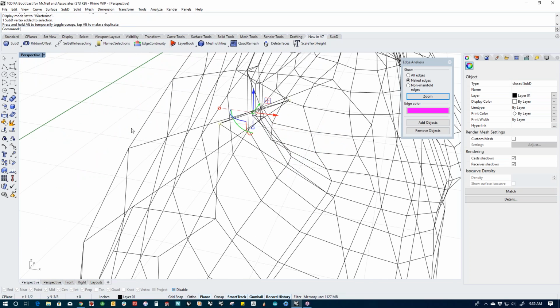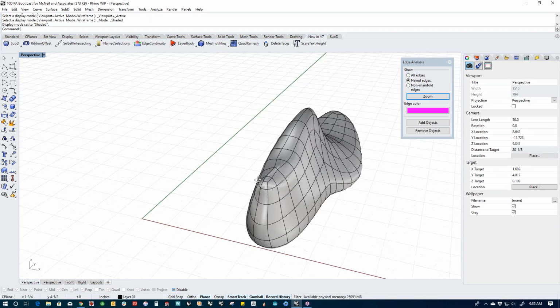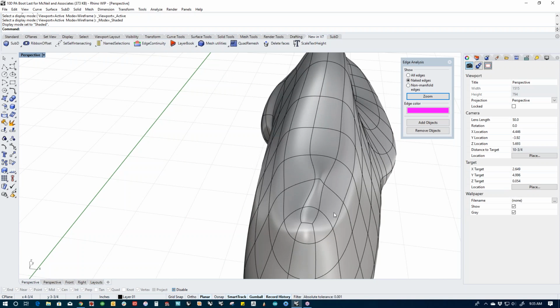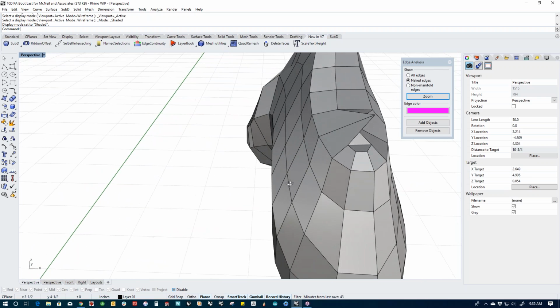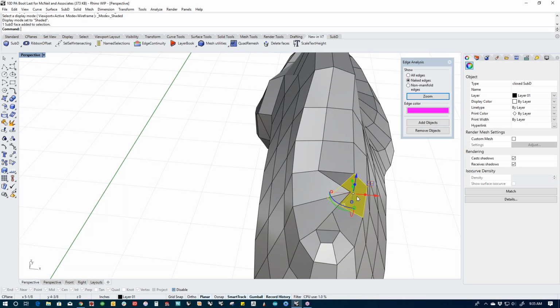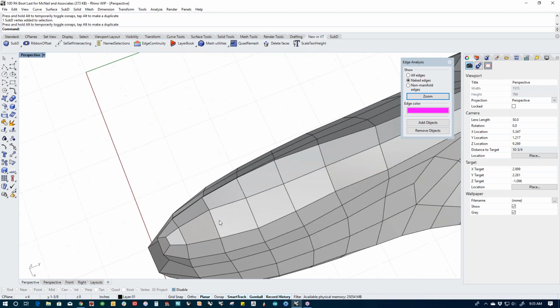But let's say that it did, and we look at the model and we can see that there's this weird pinch going on here, right? And it's hard to determine what's going on in the smooth model, but if I hit tab, I can see, oh my God, look at that. So in the mesh model, or in the control cage, if I hit shift control click and turn on one of the points, I can simply just line this back up. I can clean this up super easily.